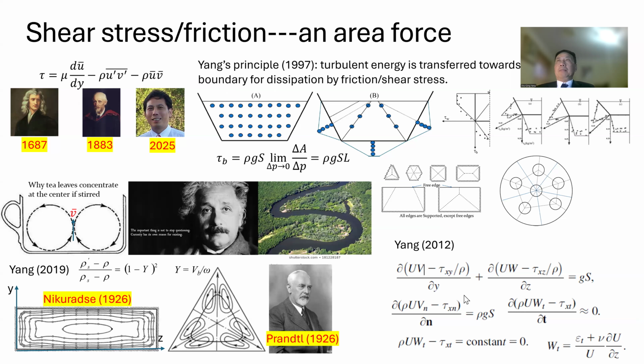And I pick up this term that Prandtl dropped, and I found this is another partial differential equation. By solving this partial differential equation, I got that the horizontal velocity should be proportional to the velocity gradient in the z direction. So here, if this direction is not proportional to your boundary, then you can observe the secondary currents. Because of this one, we have the V.